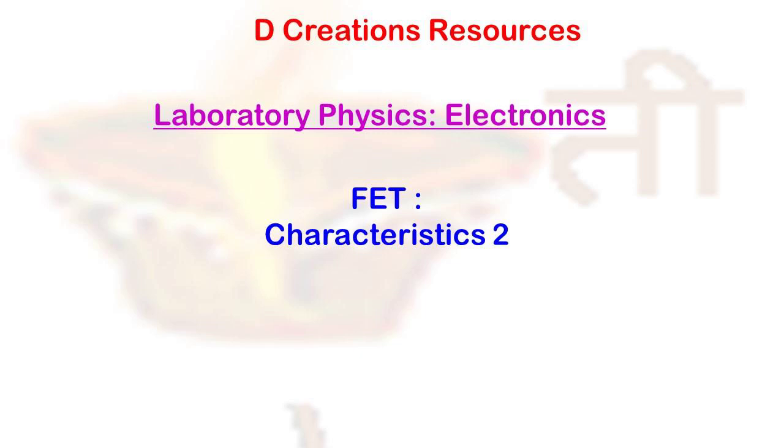One of the most important applications of JFET is the source follower, a circuit similar to the emitter follower in bipolar transistors, except that the input impedance is in the hundreds of megaohms for lower frequencies.